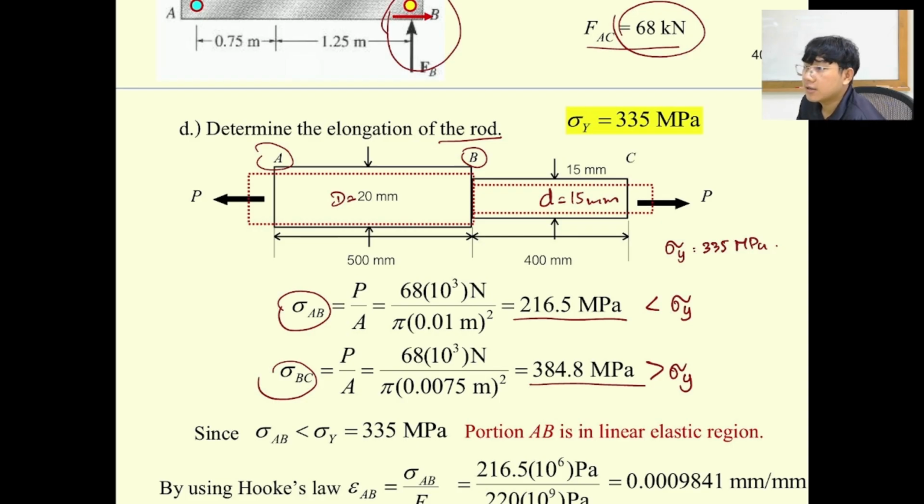Plastic or elastic? Elastic, right? So it's less than sigma y. So this one is elastic. So when it's elastic, you can just find strain by using Hooke's law. Okay, directly.